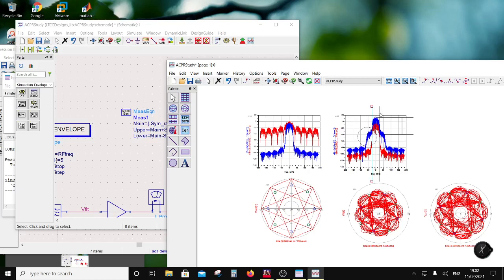And then I have taken the entire thing and shifted it by symbol rate divided by symbol rate into 1.35, so 35% excess bandwidth. So I have gone that way, and then I have also taken another which is over here. So I have got main channel, upper and lower.